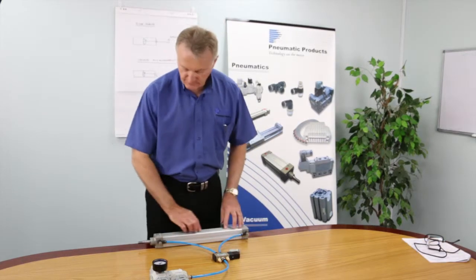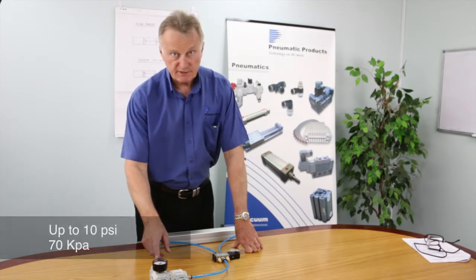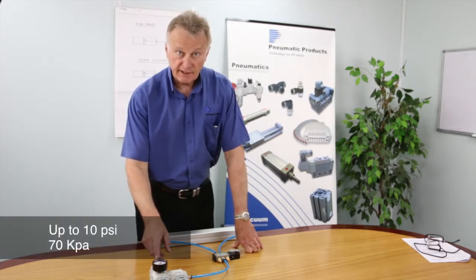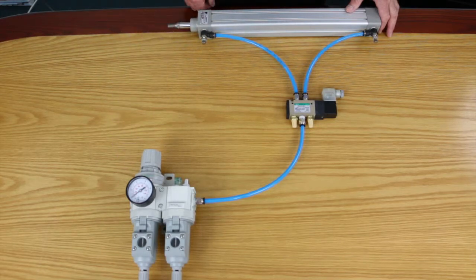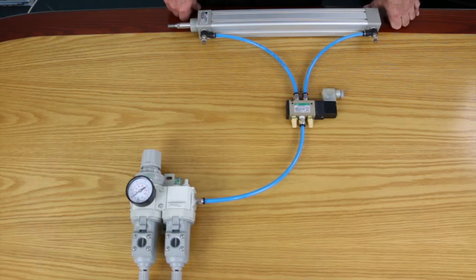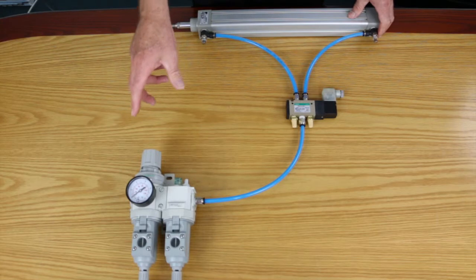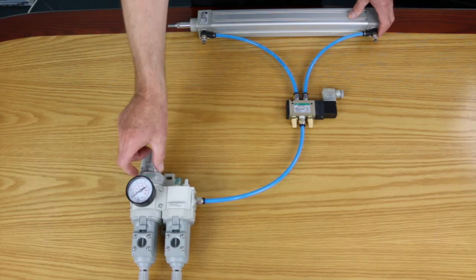When the cylinder is actuating, if you see a very large movement in the needle, say up to 10 psi or 70 kPa, then there's obviously a restriction. This should not be happening. We should only be getting about 5 psi or 30 kPa maximum fluctuation of the needle. That means we need to first of all start looking at the filter and changing the element. So the first thing would be to change the filter element.